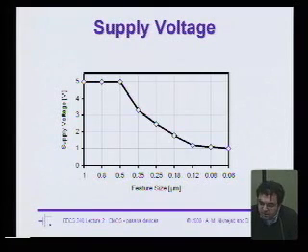And the digital people love this, right? Why is it that digital people did not mind scaling voltages? Power, right? CV squared F power. So V squared is the power dissipation of a static gate. Scale the voltage, you scale the power by the square of that. So that's great. Analog, though, really has suffered. Why is it that analog can't handle lower supply voltages?